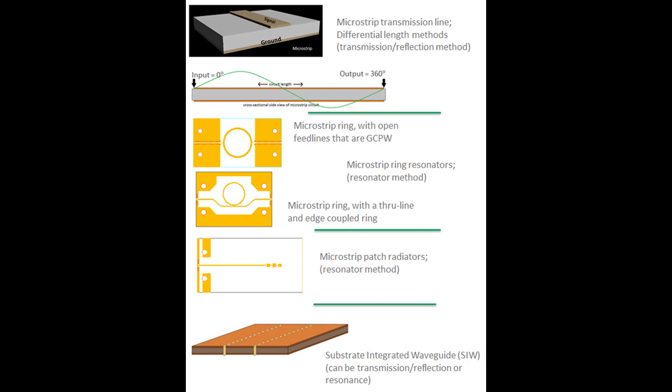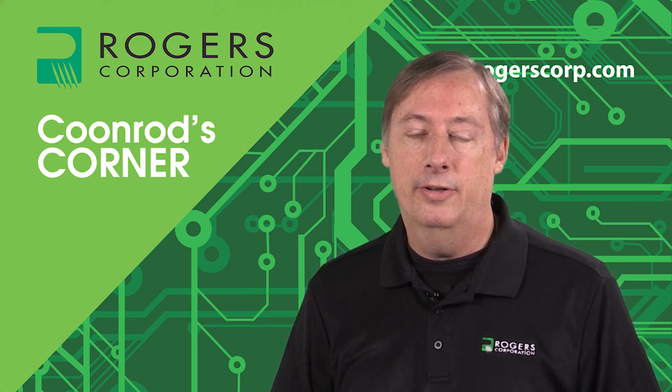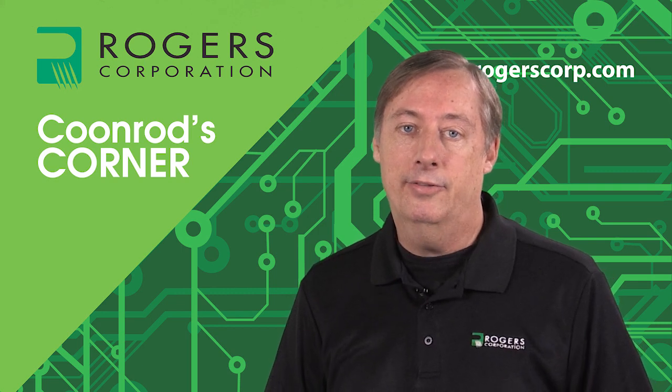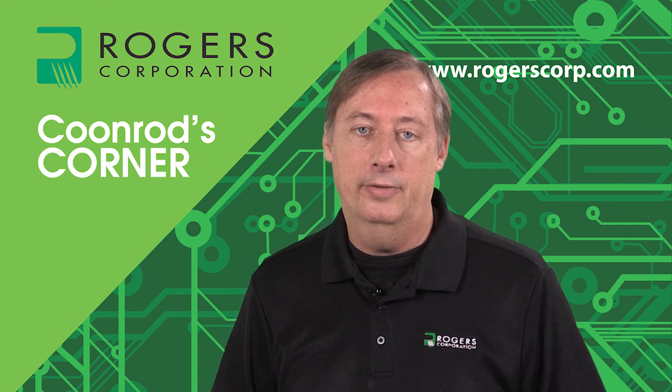So let's move on and talk a little bit more about these test vehicles and how they behave. As you can see from the previous picture, these circuits have very different designs, and because of that, the fields use the material differently. And that's also a fundamental reason why you can get a different dielectric constant from these different test vehicles.